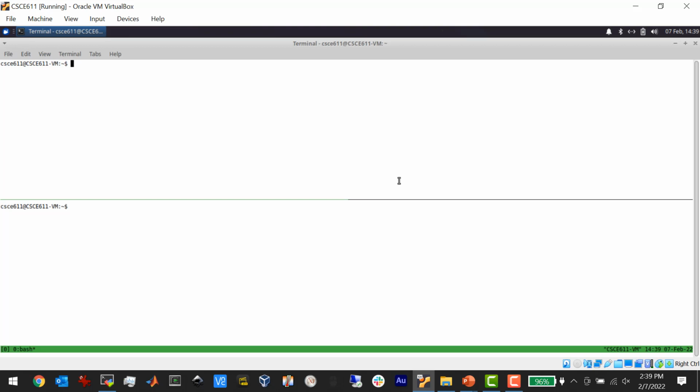But the hardware abstraction layer makes it a little bit like programming a real computer, but there's no exception handling in it. So if you crash your program, it bricks the board. I mean, not permanently, but it crashes the hardware and makes it useless until you reconfigure the FPGA or reload your software. There's no segmentation fault or anything like that. There's no safety net like you have in Linux. If you read address 0, it just crashes. In here, if you read address 0, the board just stops working.